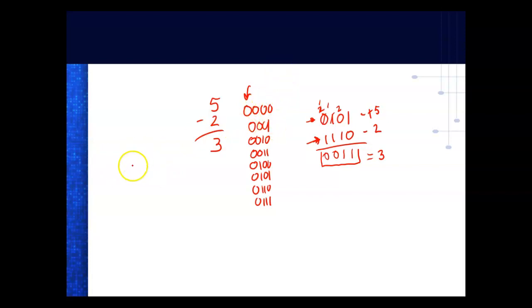So if I say 4 bits, I say 2 raised to the 4th. That equals 16. So that means I should have 8 positive and 8 negative combinations, but I don't. I have 7 positive and 8 negative, because we lose one of our positives because of what? 0.